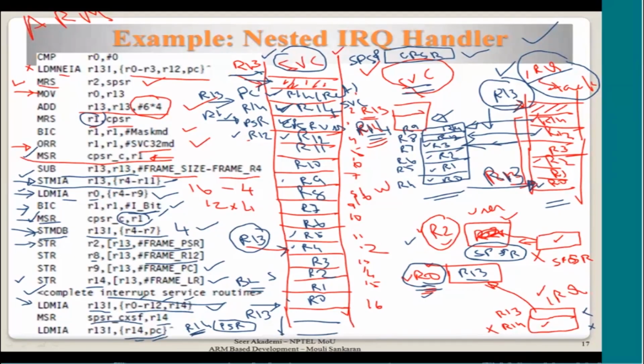with the exclamation mark. When we do a caret mark, what happens? It copies the SPSR also into CPSR. You remember that when we execute this instruction, both PC and R14 are loaded from memory, and SPSR is copied into CPSR, the user mode. So effectively we have come back to user mode now. Actually we came out of the user mode to IRQ and then coming back to the user mode to SVC, the supervisor mode. That is what is happening here.